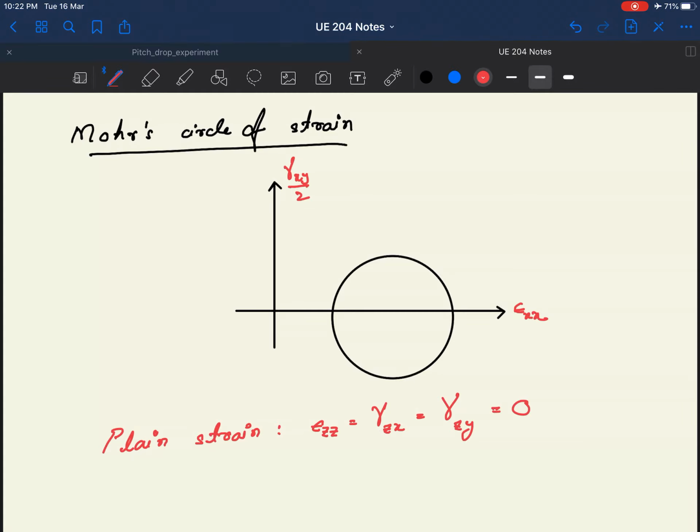So if you know the transformation, all you need to do is multiply the strain tensor by the appropriate transformation matrix to get the new one. So for three-dimensional cases, it does not make enough sense to go and learn the generalized Mohr circle.